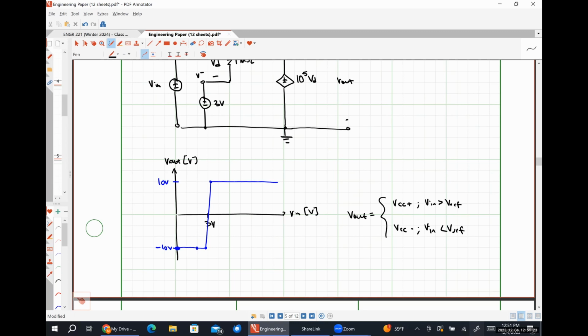Walker. V ref. Reference voltage for both. Yes, sir. So, when you just said it, but clarify, for VA, it's so close to the reference. It has to be incredibly close. What does that make? Wouldn't that equate? Wouldn't it make like 0? It would make it 10 to the 5 times whatever Vn minus 3 volts is. But I mean, it has to be within a few microvolts of the reference voltage to not saturate.